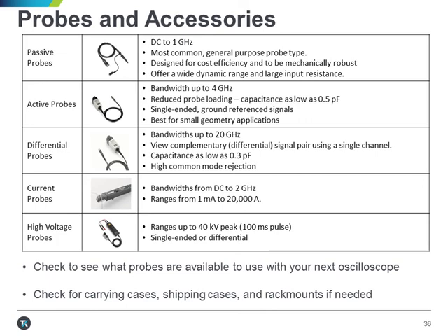In today's scopes, the instruments and probes can communicate with each other. This allows the scopes not only to sense the right scale factors, but also to change the attenuation factors or ranges on the scope's front panel. The scope can tell you right on the screen when a probe is open, and it can guide you through procedures like current probe degaussing.